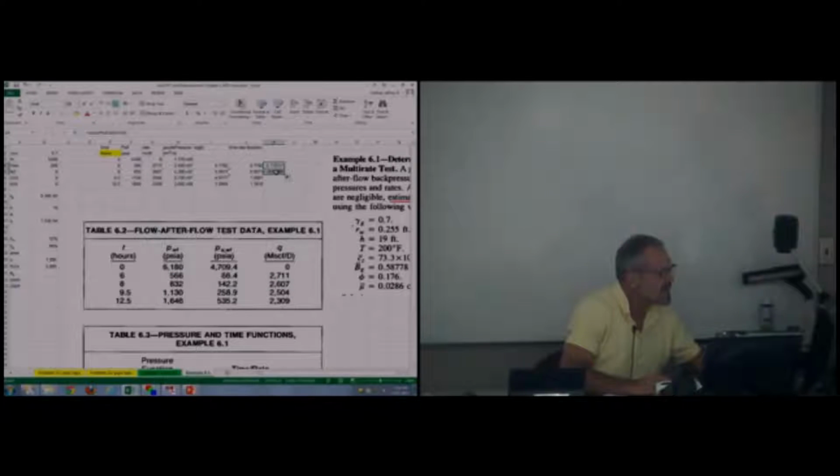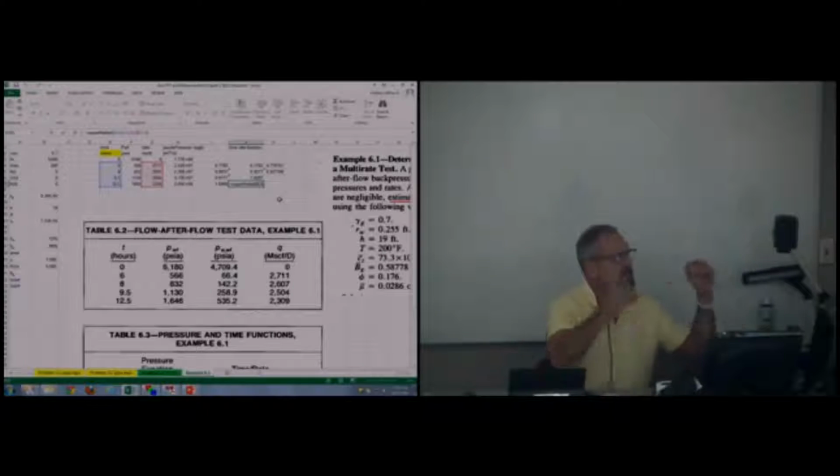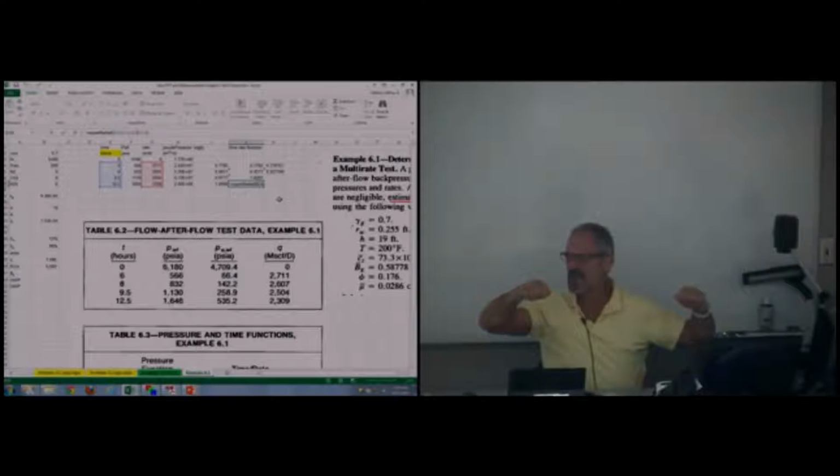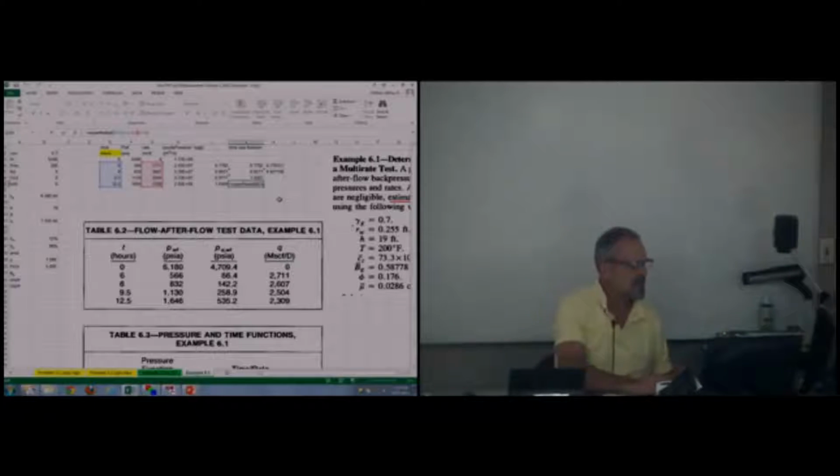But if I copy that down here, I have to make it for that and that. That'd be the manual way to do that. See that? Then I get the 9271. But to do it automatically, I just have to make sure that I anchor back to the first point and make it relative to the last line, and then I can copy up and down.